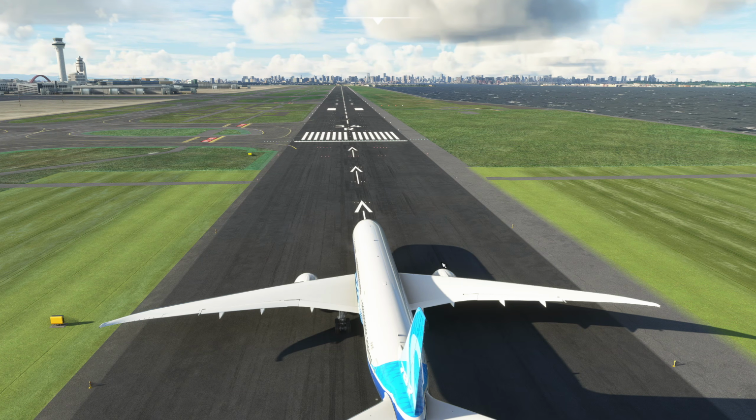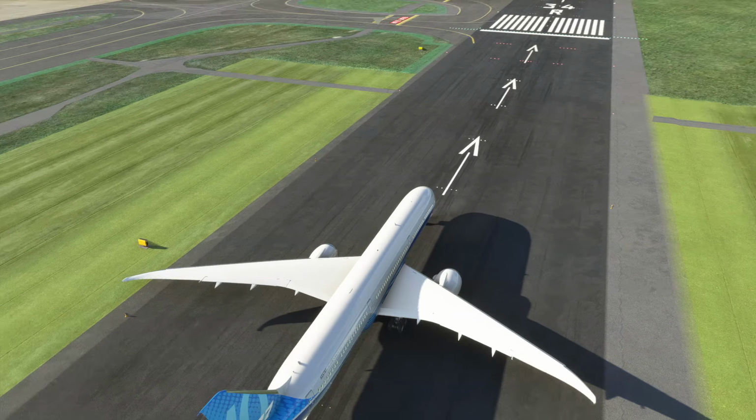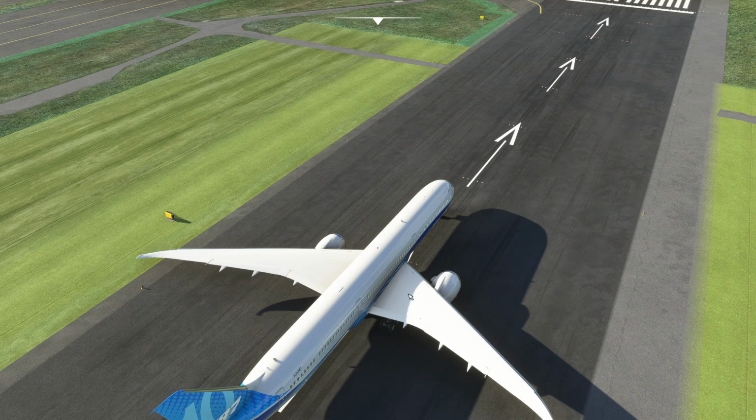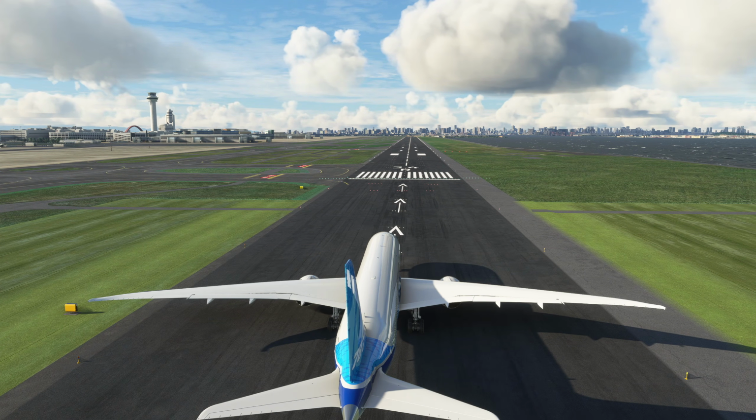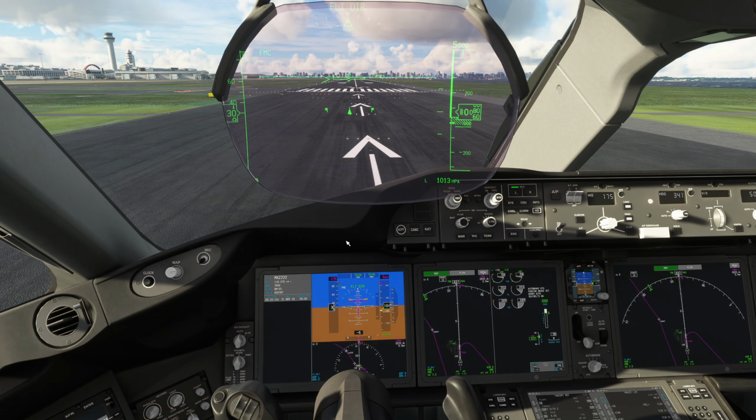However, when you first set takeoff thrust in a 787 in a crosswind like this, and I'm curious to see if this model has it, I doubt it, it's a very specific thing, because of the way the engines are blanked out from each other, it can actually generate a weird effect where the airplane will turn downwind initially, and then that swaps over as you accelerate, where it suddenly tries to point into wind. So you end up at first having to use into-wind rudder, strangely enough, and then swapping over to left rudder. Basically, don't overthink it. You just keep the airplane straight by looking out the end of the runway, but don't be surprised if you have to reverse the rudder during the early part of the takeoff roll.